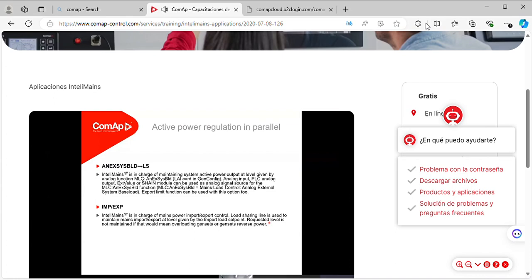So we can again do that by bringing in actional base load control. We can go to the set point and configure an analog input like a standard potentiometer. Maybe you can use a 1K pot or 2K pot. That potentiometer can be mapped to the base load of, say, 0 to 100% of whatever range you want to operate, and that can be connected to an external base load